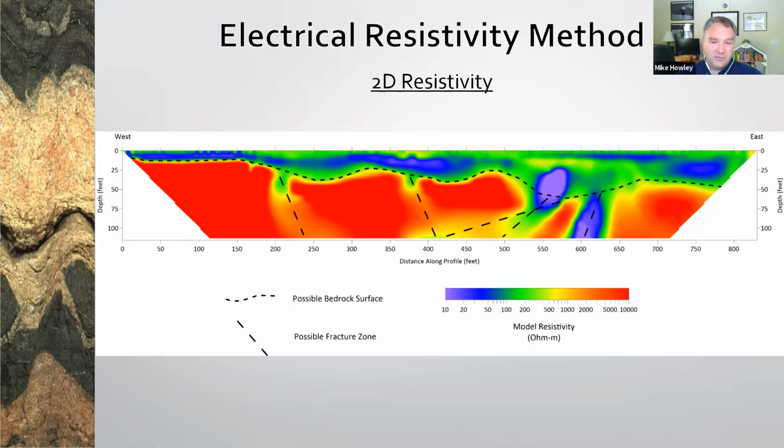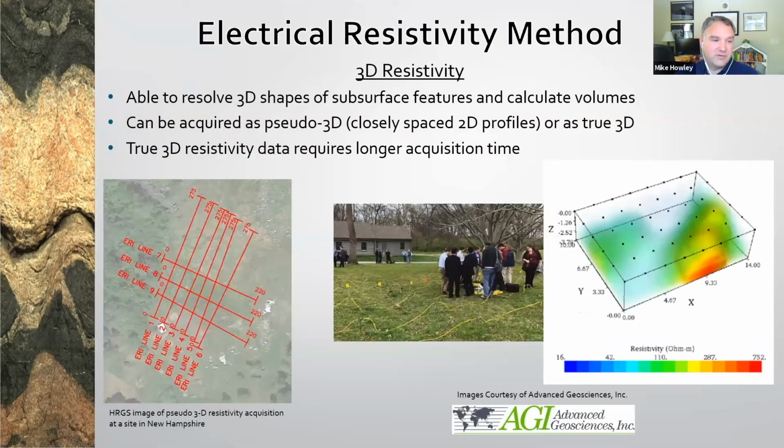The primary limitation of a two-dimensional resistivity survey is that when the inverted resistivity section is calculated, the apparent resistivity measurement is assumed to be directly under the profile line. In reality, the area of an apparent resistivity measurement is more like a flashlight shining downward. Resistivity changes off the line will impact the apparent resistivity measurements along a 2D profile. The resistivity method does give a good picture of the electrical structure of the subsurface, but to get a better understanding, we have to go to a 3-dimensional resistivity survey.